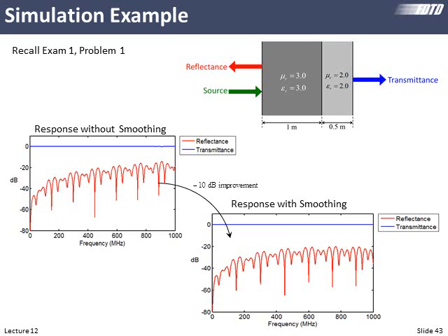So a real simple simulation. We have slabs of two materials. Depending how we choose our grid resolution, let's just say we can't simultaneously represent both of those with an exact integer number of cells. Although in this case, since one layer is exactly half of the other, we probably could pick a grid resolution intelligently to do it. But let's just say we can't. And we simulate these. We actually do see quite a difference in the spectra between the two. And comparing them to a higher resolution grid, we see about an order of magnitude improvement for a given resolution. So this does help us a lot.